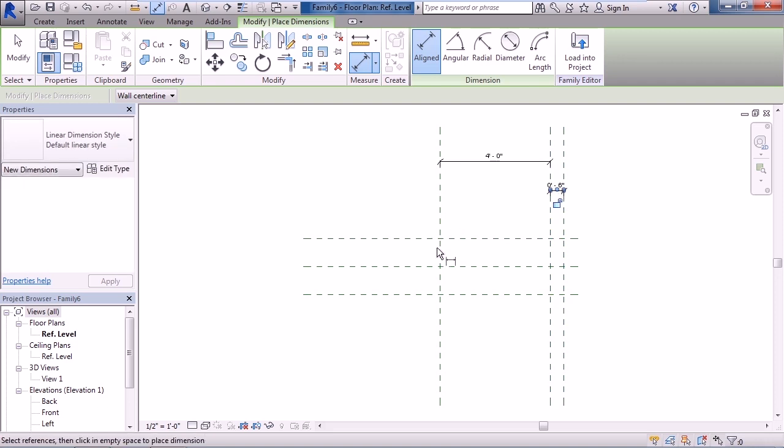there. Now for the 3 horizontals, we're going to make a continuous dimension from one to the next to make them equal distance. So click the bottom horizontal line first, then the middle reference line, then the top reference line. Then move back over the dimensions and left-click to place.